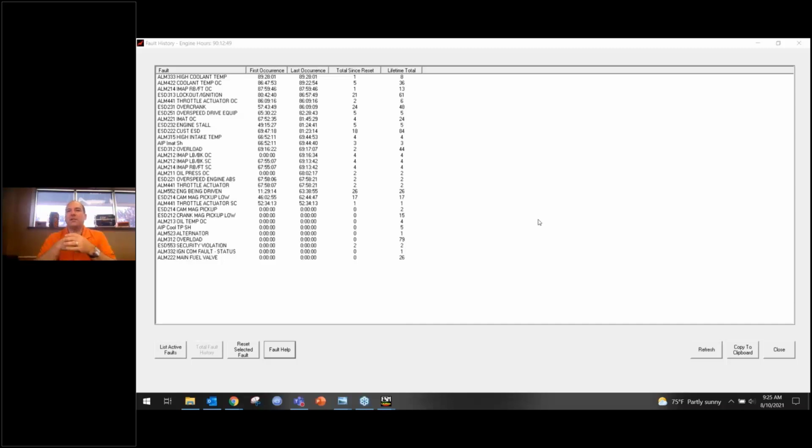My auxiliary circuit is important for my combustion temperature, or what's going into the combustion chamber for my air charge. I want that to be right at a target, and it's going to heat up as it goes across the turbo. So in this scenario, they said, nope, I don't trust your auxiliary cooling sensor. I'm just going to go ahead and disconnect it. Is that going to cause the engine to shut down, and have that alarm code 422? The answer is no. So some of you that said no, well, it's kind of true at the beginning.